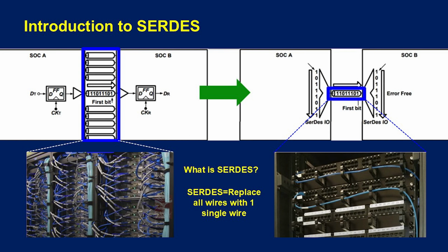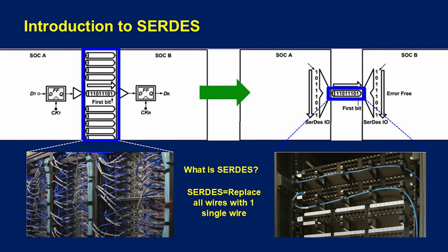That is where Serdes was introduced long back, right. This Serdes is not new. Serdes introduction happened around, let us say, the 60s, 70s, 80s, 90s time frame. People started introducing Serdes in all these interface data transfers, right. When we talk about Serdes, the data which is in parallel form in the transmitting device gets converted into serial form into the channel, and then from the channel it goes to the other side. Now, how to do that?